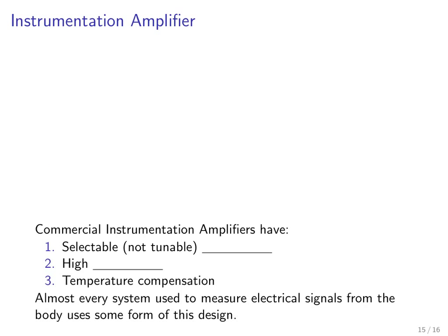So let's put together all these circuits that we've just learned about in order to represent a modern instrumentation amplifier. On the input, as we had before, we will have buffers. Then we'll have our differential amplifier stage right after that.